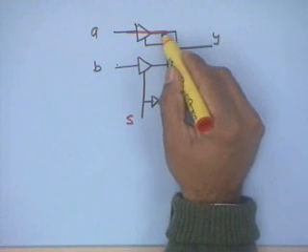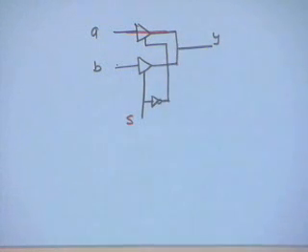The primary thing is, you can actually connect two outputs together of tri-state buffers. Typically for a logic gate, you cannot connect the two outputs together. The reason you cannot is one is going to drive the other. If one is at a 0 and the other is a 1, you do not know what the output is going to be. Whereas here you can connect the two outputs together.